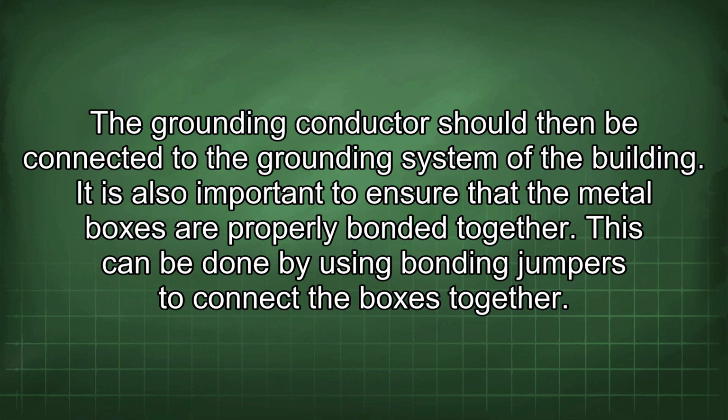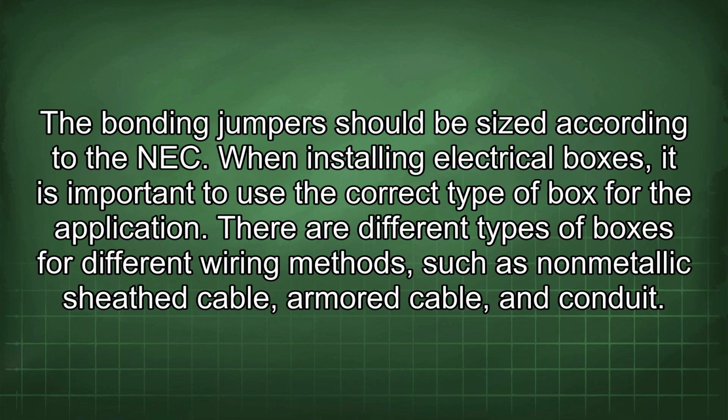It is also important to ensure that the metal boxes are properly bonded together. This can be done by using bonding jumpers to connect the boxes together. The bonding jumpers should be sized according to the NEC.